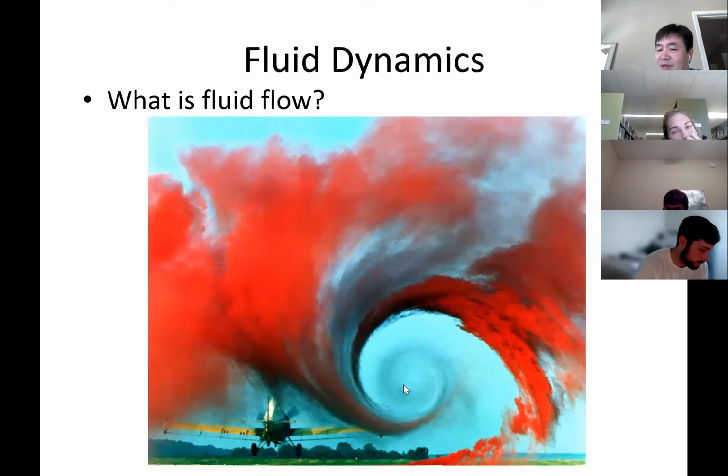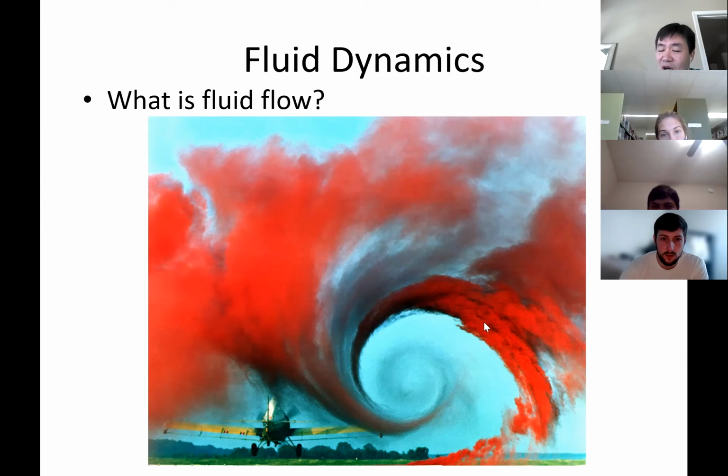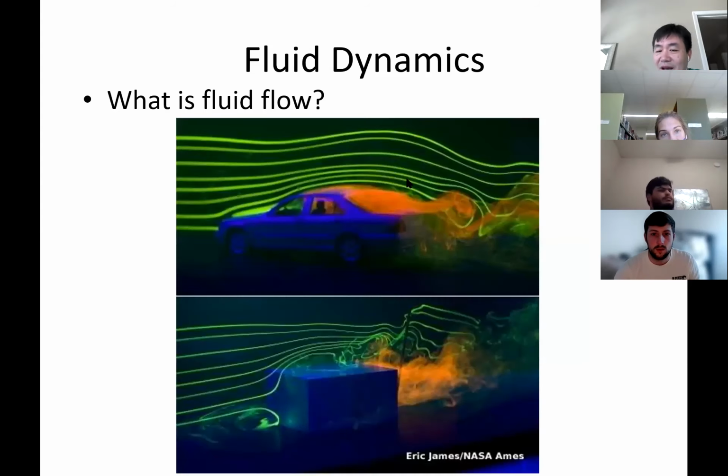The vortex center has a low pressure than the surrounding. Everybody, you guys follow me? The vortex center has a low pressure. Wherever you have a vortex, you have a low pressure. Just remember this: hurricane, tornado, whatever. You have a vortex, then you have a low pressure. Same thing here. You have a vortex behind the car. You don't have a vortex in front of the car. That's why behind the car, you have a low pressure region here in the wake.